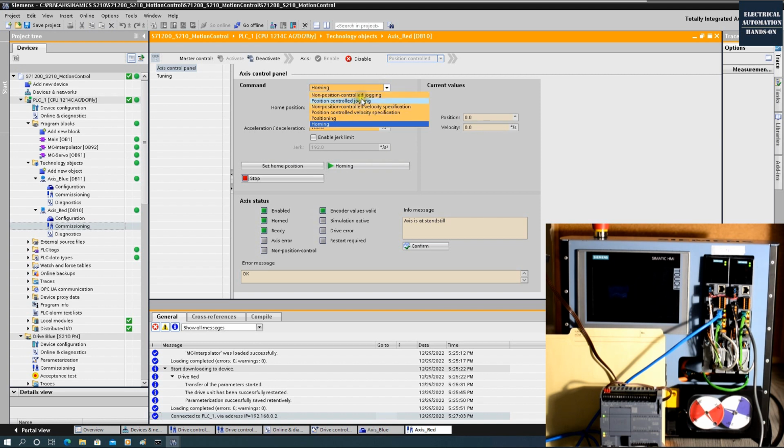So there are a couple of selections here. For the position relative or absolute control, we can select this positioning. Then we can set the velocity and the distance. For example, the velocity I can set, okay, 900, not too bad, and we can travel 10 revolutions. And now we can see if I click this absolute, it will travel to 3600.